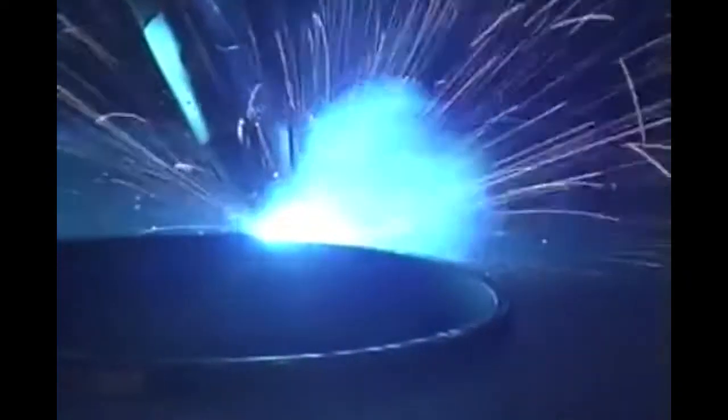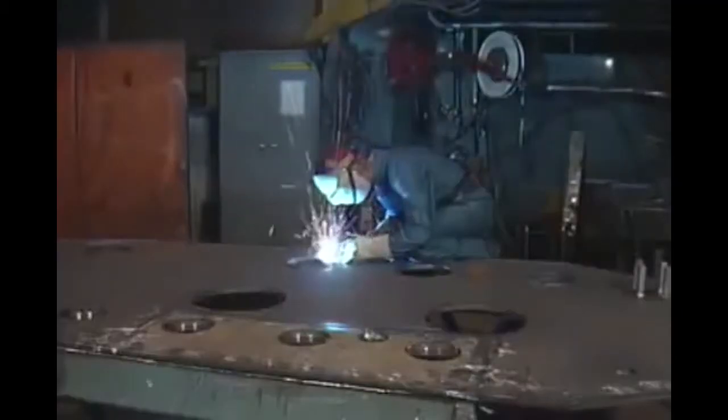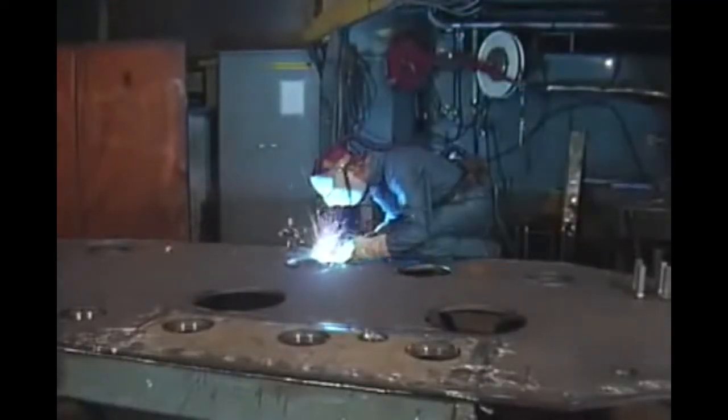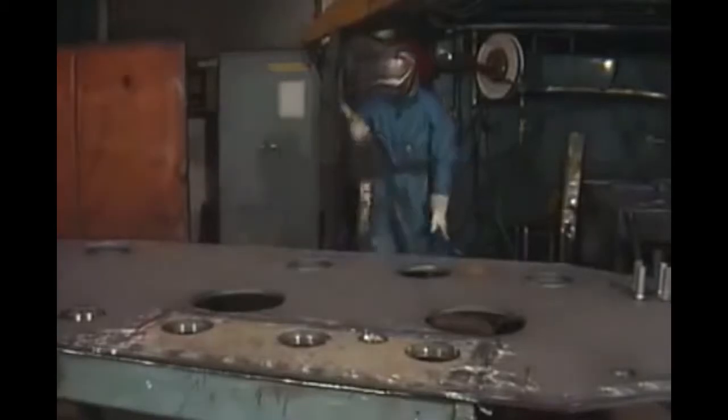are always observed. To ensure the highest quality, regular tests verify the welder's workmanship on stress-resistant welds, which are vital to a transformer's construction. The welds themselves are also typically subjected to penetration, X-ray or ultrasonic spot checks.